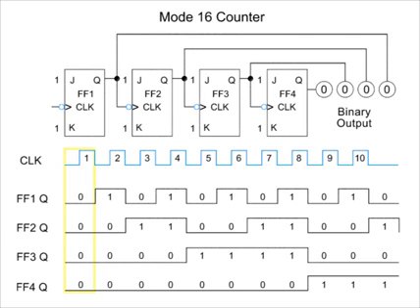As pulse 1 arrives at the clock input at flip-flop 1, it toggles on the negative edge. The output at Q1 will go from low to high, or 1. Thus, the counter will be at 0, 0, 0, 1.